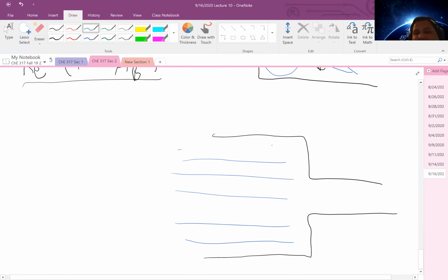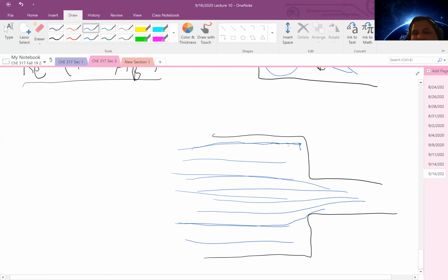And once again, it's not going to realize there's a wall, turn on its turn signal or not, and take the left. As much as we'd like to think that fluid is intelligent, it's not. What's most likely going to happen is there's going to be a compression effect. And at the same time, the fluid that strikes these dead sections is going to end up with vortices and eddying occurring there to, one, further dissipate energy, increase shear at those edges, and it's also a natural result of the compression that exists in those flow sections.